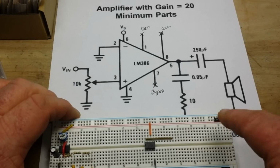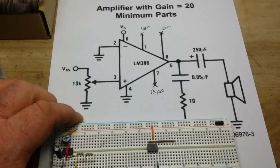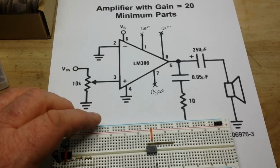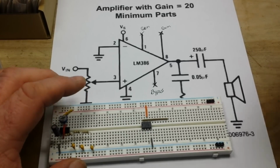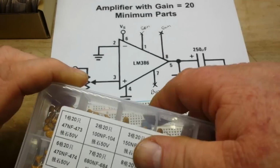Then we need a 0.05 microfarad. Why would you say 0.05 microfarad? Because now you got to make me do internal head math. It's 50 nanofarads, I think. I'm sure somebody will correct me if I'm wrong. I probably don't have 50 nanofarad, but I probably have 47 nanofarad.